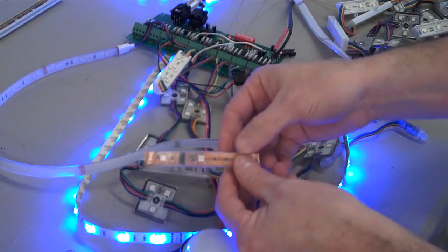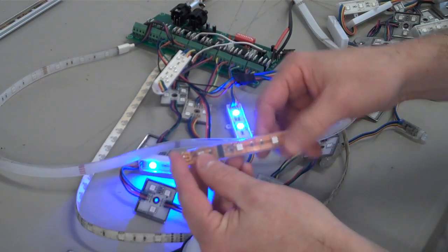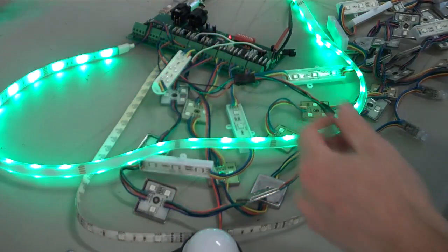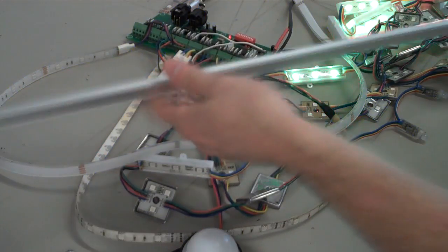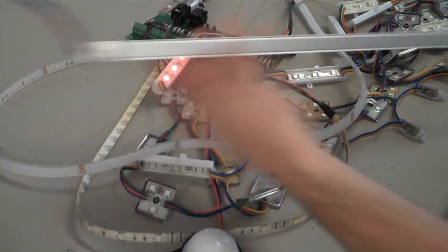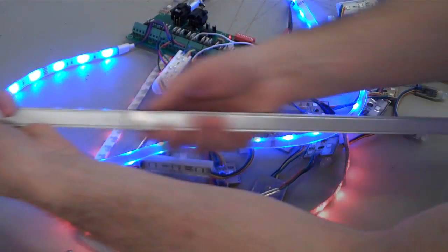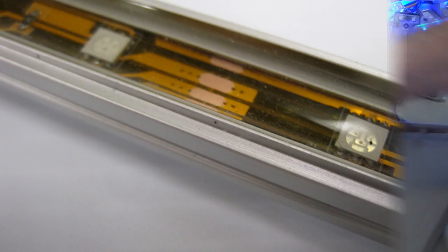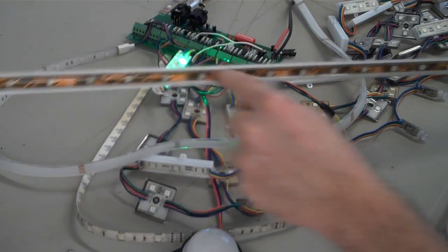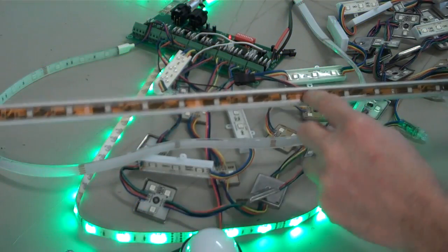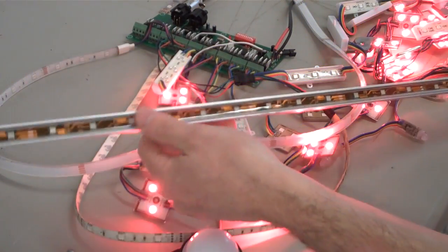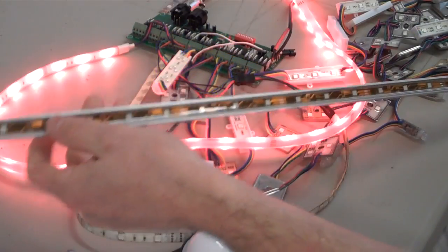And the same applies to these. Is not as reflective as the white. Now, a slightly hybrid version of the strip is strip mounted to a solid carrier or a channel. And in this particular case, you can see that there are some little mounting tabs. And this is simply 50/50s on a strip that are siliconed or epoxied into this channel. Very rigid. It ensures that there's no bending, which could damage the devices.